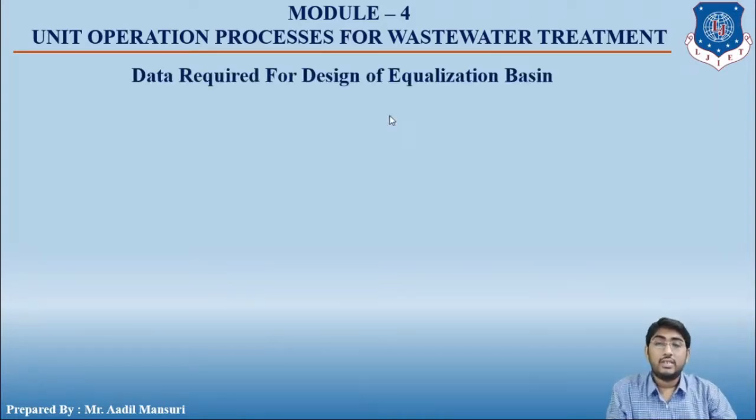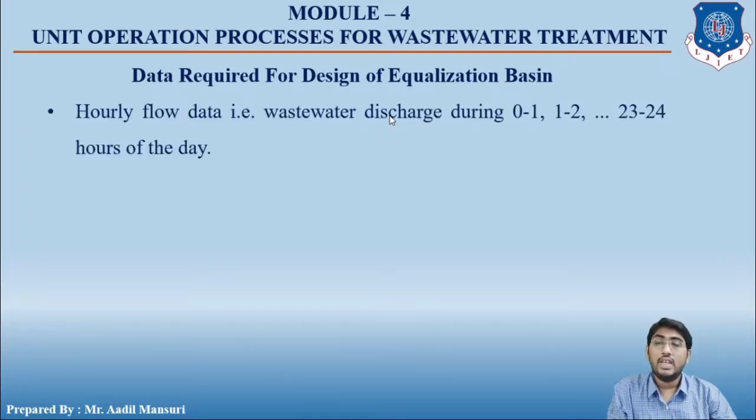So next is data required for design of equalization basin, right? So first one is the hourly flow data, that is wastewater discharge during midnight to 1 o'clock, 1 o'clock to 2 o'clock, so on till the 23rd, that is the 11 p.m. to midnight. Okay, so you need all those data, that is hourly data.